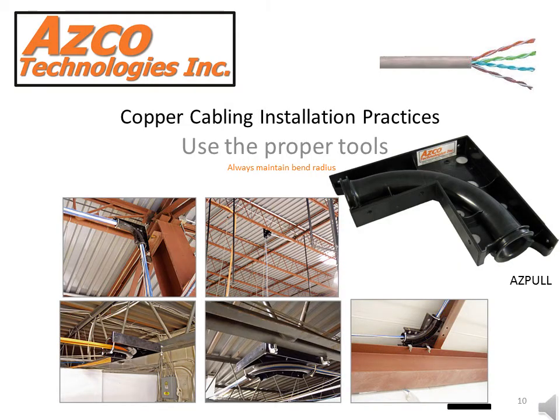Use the proper tools when pulling cable. Make sure you don't compromise bend radiuses. This tool, the AZ Pull from Azco, allows you to pull vertically or horizontally around corners or up to the ceiling, etc., without compromising the bend radius of the cable, and of course having less tension on the cable during the pull. Makes it a lot easier as a one-man pull as well.